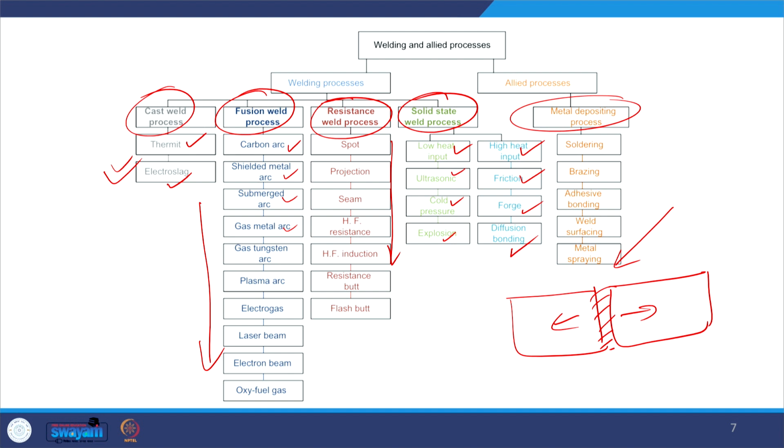In electroslag welding, the heat is generated at the interface and things are brought to the molten state, with melting of the parent metals and the filler metal both, but the cooling rate experienced by the weld metal during solidification in electroslag welding is similar to that of the casting process.